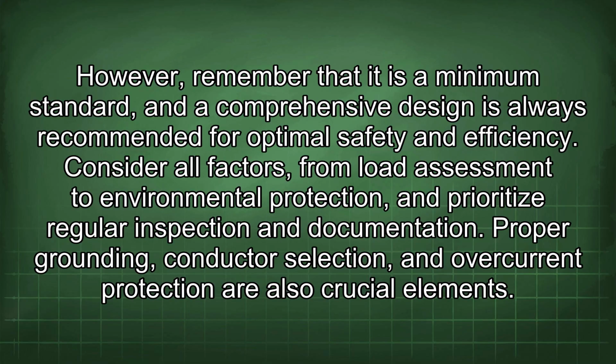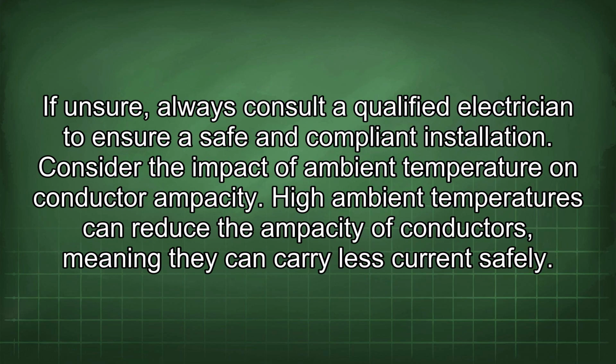Proper grounding, conductor selection, and overcurrent protection are also crucial elements. If unsure, always consult a qualified electrician to ensure a safe and compliant installation. Consider the impact of ambient temperature on conductor ampacity. High ambient temperatures can reduce the ampacity of conductors, meaning they can carry less current safely.